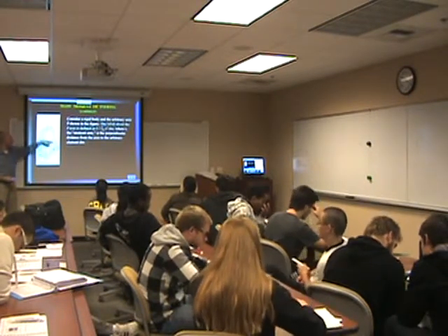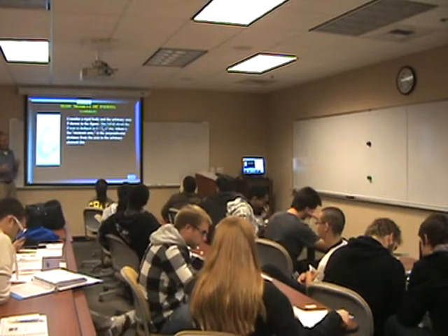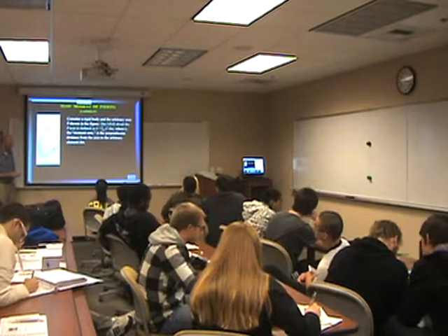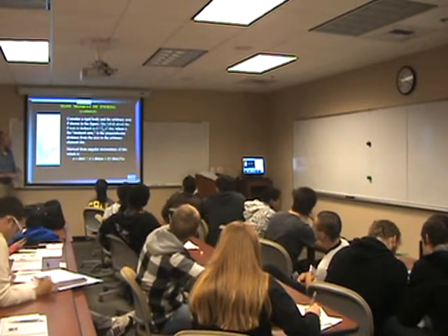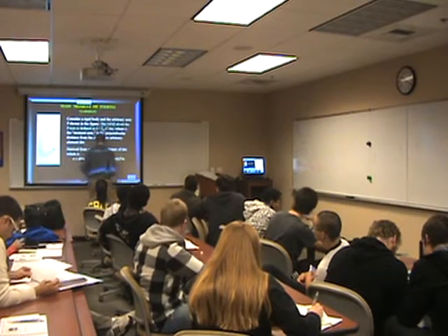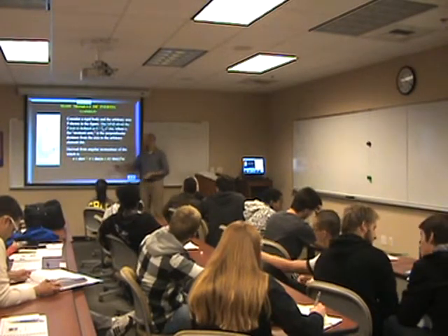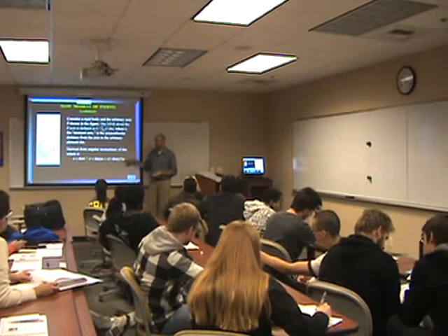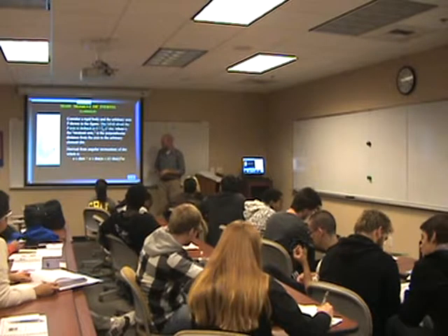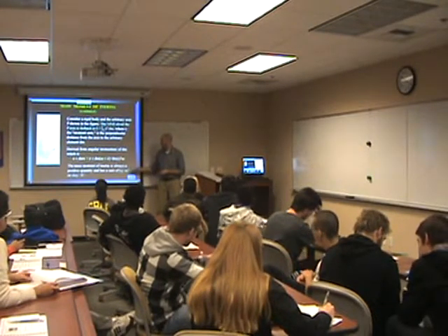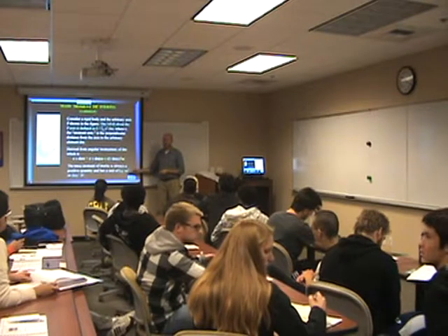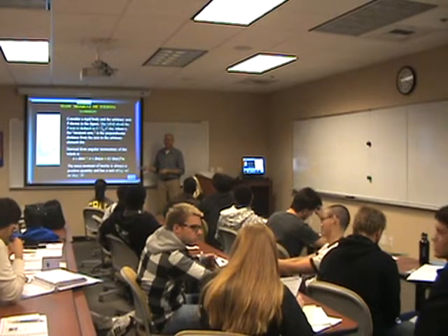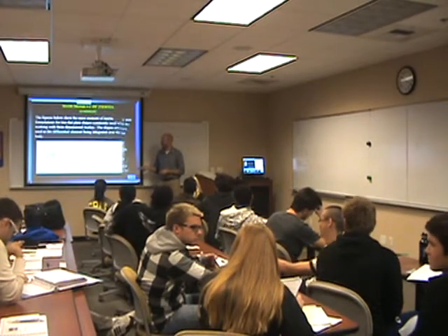So how would we add up all the little masses? Integral. We take the integral. So we do the integral over the entire element. And so angular momentum, r cross mv. So it's r cross dm omega cross r, or dm r squared omega. The velocity is r omega. And so that's how we get the r squared. It's in kg meters squared. Since it's meters squared, it's always going to be positive. Or slug feet squared, which we don't like, but that's what it is.